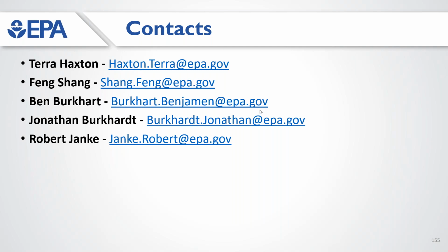EPANET doesn't have VSP modeling capability. But you can try different pump settings to see how it works, or you can use some control, if-then, to change the settings. Yeah, I know it's because most commercial software already have VSP. Bentley has a patent on it, but it's not currently in EPANET. But from a trial and error point of view, you can use some pump settings to see how it works out.